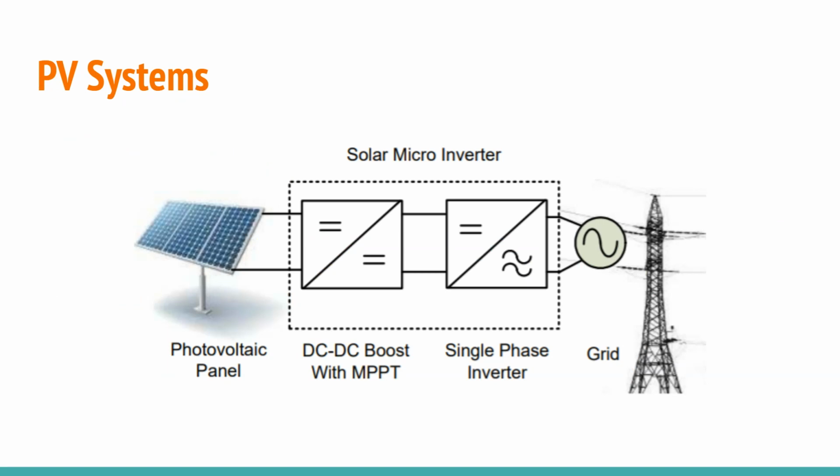So PV and solar systems on a utility scale tend to support power levels between 100 kilowatts and 1 megawatt. The latest trend connects the PV system to a battery in order to store any excess energy. This battery can also provide power to the grid in case solar panels are insufficient. The solar panels are connected to a DC to DC boost converter for the next stage.